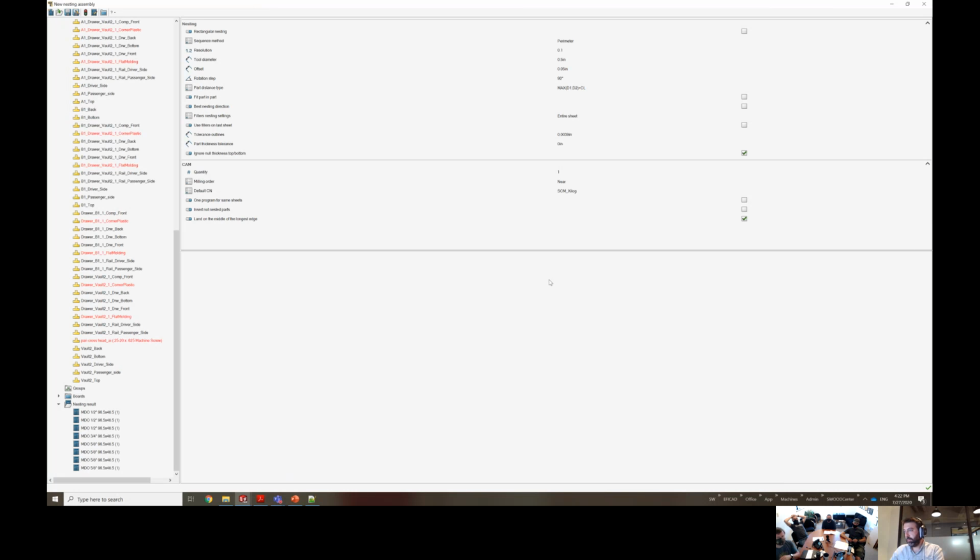Okay. Now, is it doing all the work with one tool before it goes to the next? At least, I mean, drilling all the 1/8 holes before it goes to doing outlines. Yeah, we optimize when we combine the part programs in the nesting, we optimize by tool.